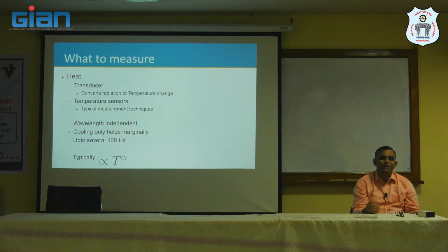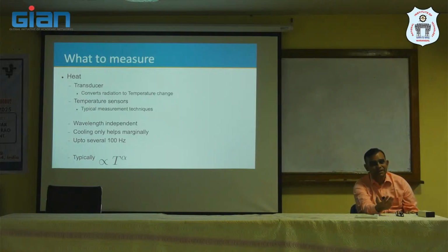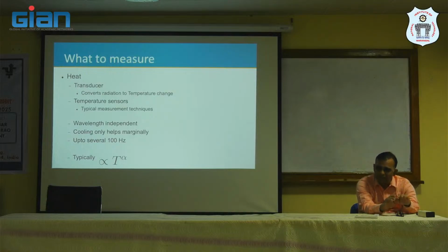So, quite often in many of the other sensors, like wavelength dependent sensors, we try to cool the sensor to record the infrared. To some extent it also helps because, at room temperature, at any temperature, we already have thermally generated charge carriers as well. In any semiconductor, heat itself leads to electron hole pair formation. Ideally, we would want to measure electron holes which are just being produced by my radiation, not by my heat.